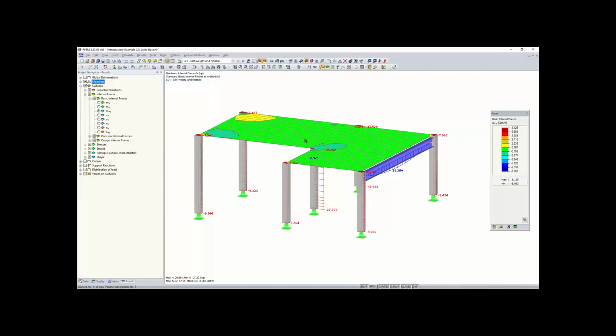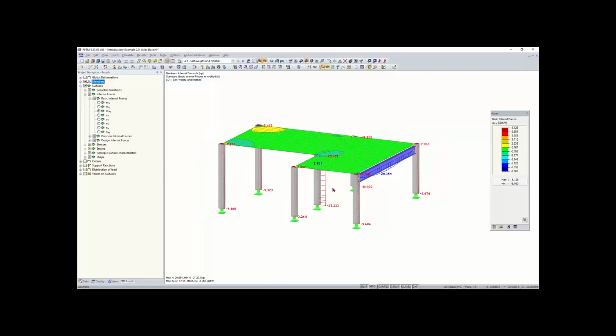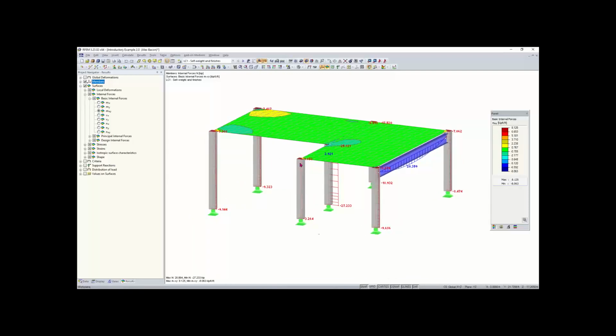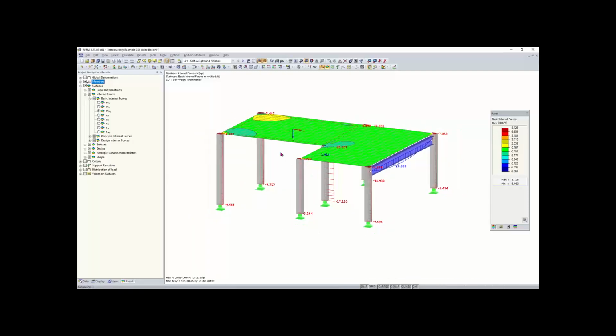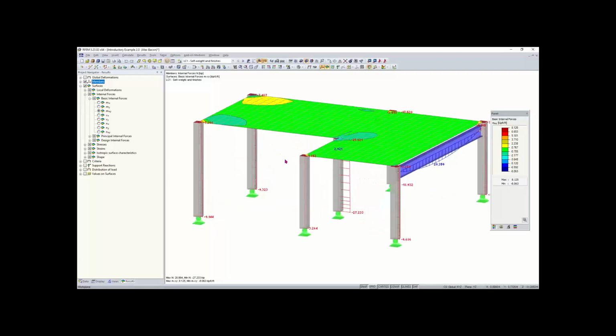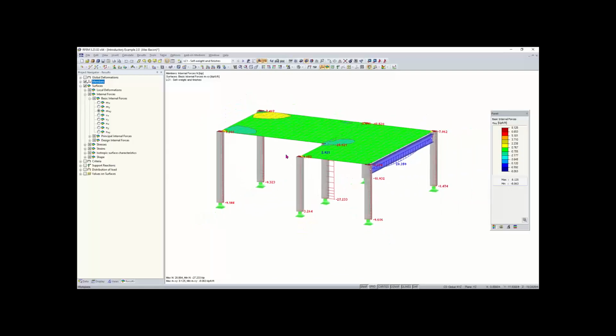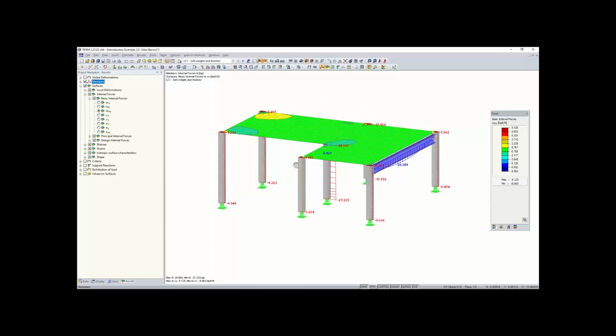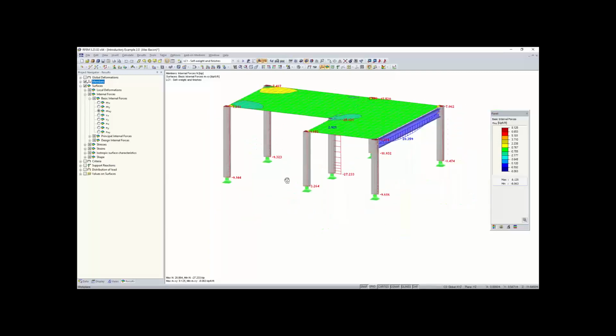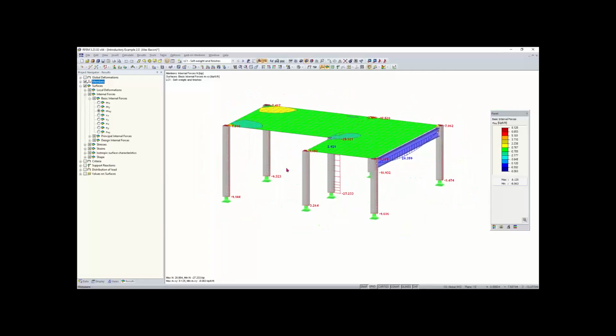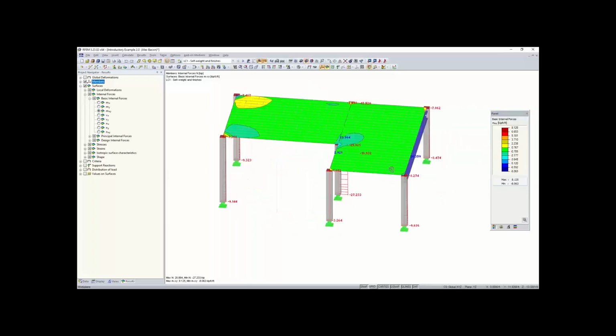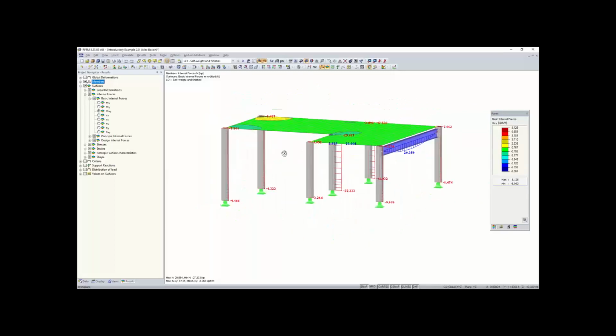Also, controls, very important. So if you like to interact with your model, if you have a scroll wheel on your mouse, you can zoom in and out with the scroll wheel. Clicking down the mouse scroll wheel will let you move the model in translation. And then holding control and clicking down the scroll wheel at the same time will also allow you to rotate your model.